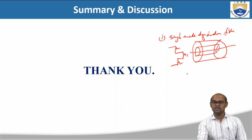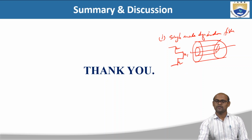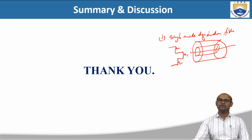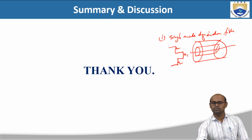We found out that in the propagation of light in single mode step index fiber, the numerical aperture is very small, because there is only one mode for the propagation of light. The numerical light gathering ability is very small, and hence we need to use costly laser diodes for launching light. So it's not very good for the application.